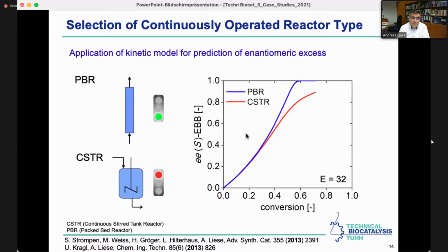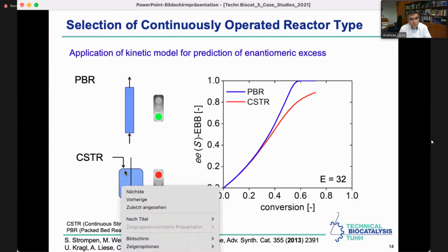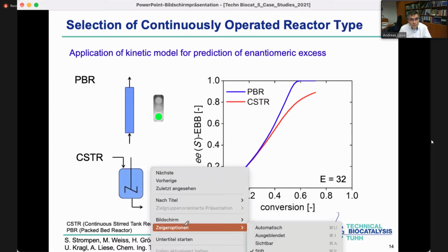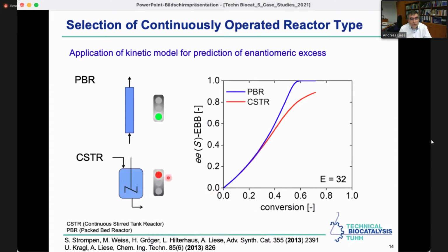And the explanation, which we had in detail in the lecture, is that in one residence time, we're working under outflow conditions here in the CSTR, we always add racemate to the already ongoing resolution. And therefore, we're always adding the wrong enantiomer during the course, generating the outflow conditions.